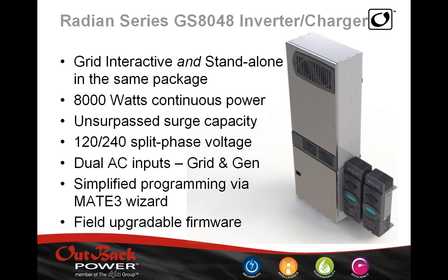Also, this inverter is an 8,000 watt inverter, and it really consumes very little compared to the output power that it can have. It only consumes 30 watts. It can take very high inrush currents. Although the continuous rated power is 8 kVA, the surge power is almost 17 kVA.